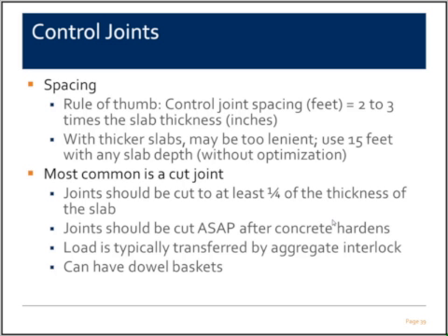At these joints, load is typically transferred by aggregate interlock. In some cases, especially in unreinforced concrete slabs, they may put dowel baskets at the locations of the control joints to help with the load transfer.